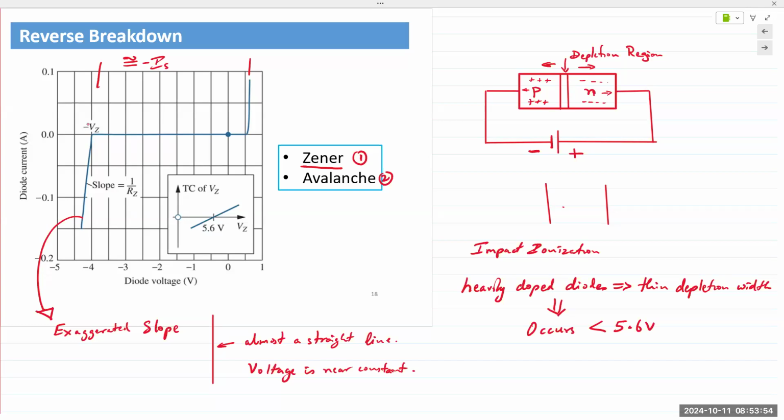So there are several different applications that you can use in several different diodes that will match those applications. So in your lab kits, sometimes if the manufacturer or supplier does not have enough of a single type of diode, they will send in other kinds of diodes. So in your lab kits, you have the small diodes. There's a set of 4 black epoxy packaging with a gray band. It could be 4001, it could be 4002, 4005, or 7, would not really matter. The forward characteristic of the diode is exactly the same. It's the reverse voltage capability that is different.